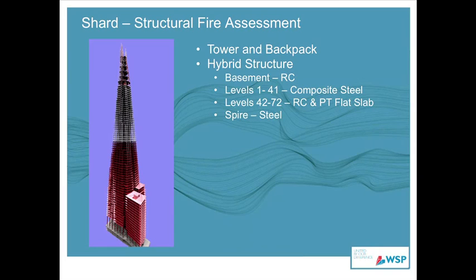This is because we can then get more floors into this portion of the building. And also that added mass that it provides helps damp down accelerations, which are so important for tall buildings under wind. And then eventually at the top of the building, we transfer back to steel for the spire of the building.